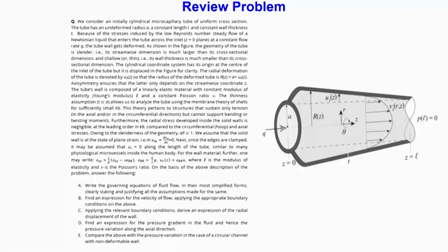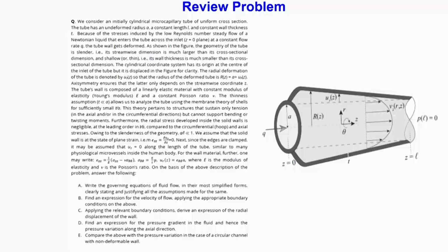We assume that the wall is thin, and therefore you can use the thin walled pressure vessel model, or the mechanics of material model, in undergraduate texts also known as strength of materials, as a thin walled cylinder or thin vessel model, where the stress and the strain can be written in terms of the pressure.